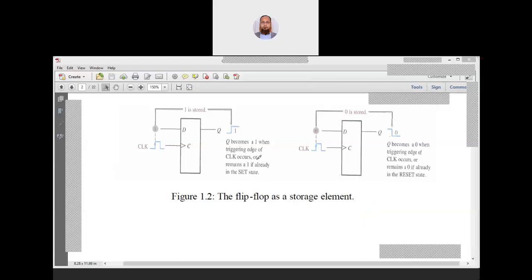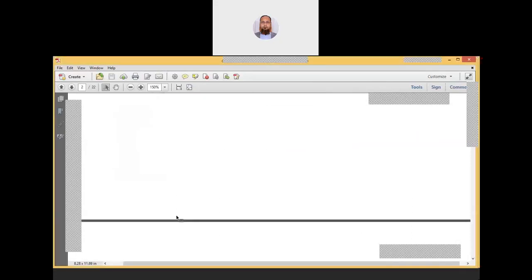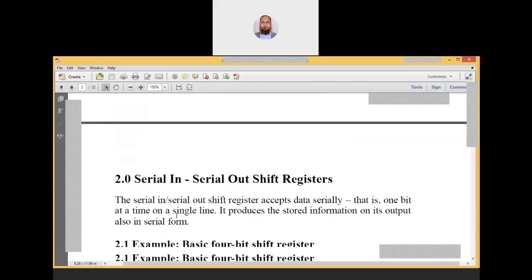Only there is an inverter between J and K that makes it a D flip-flop. So whatever input we give, at the appearance of the clock the data will pass to the output side. This is how the data will be transferred from the input to the output side.